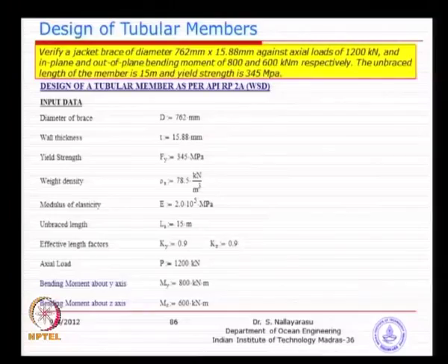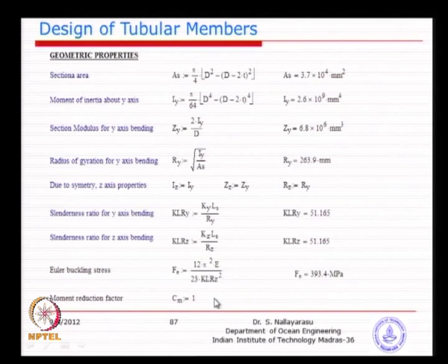So, basically the K factor table will be given if required. You need to understand that reading the words is very important, because you have your answer there only. So, you read jacket brace K factor is 0.9 or 0.8 depending on whichever the situation, and select that K factor, that is what I have taken, and then proceed with the simple procedure of trying to find out.